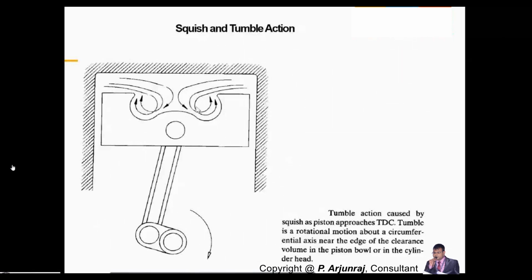for the combustion to take place. But when there is a reverse squeeze, then it will spread the flame, and again the flame will travel a long distance. Okay, so that will also create some issues. So it's always good to arrest the reverse squeeze, whereas you need to encourage squeeze, or design the system in such a way that you provide a squeeze for it.